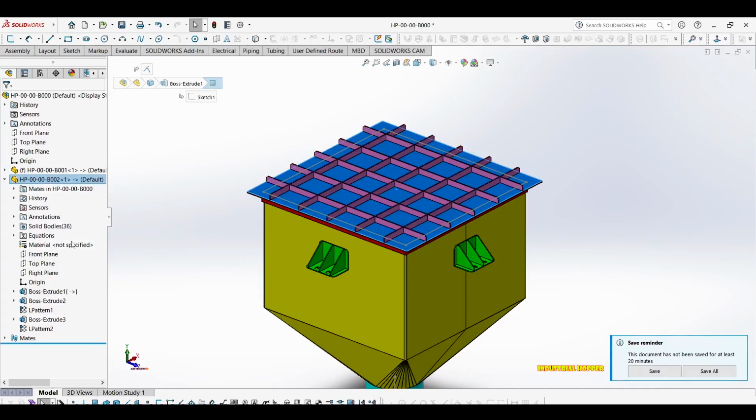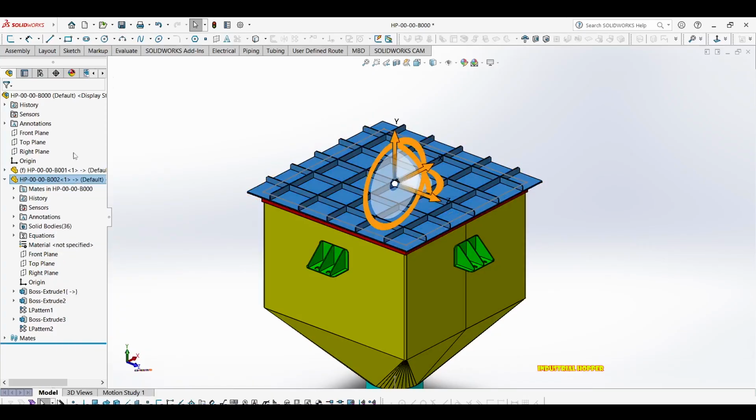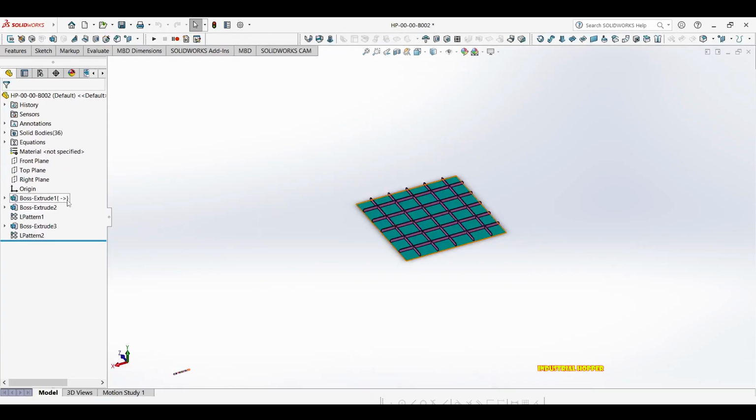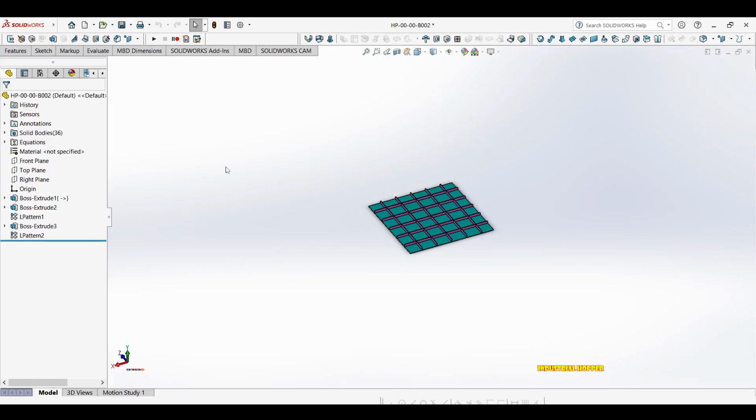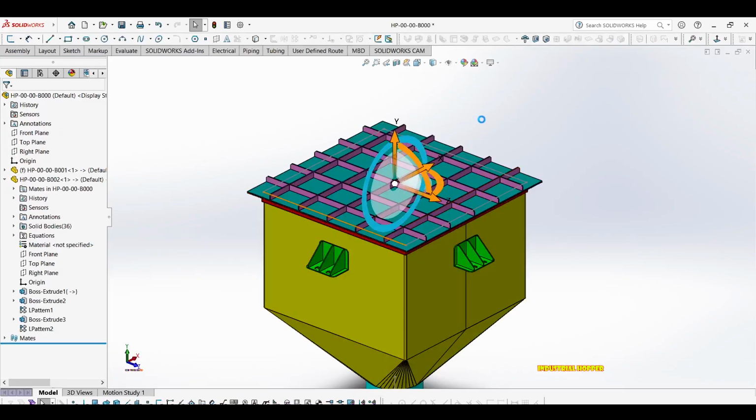And now your references, let's go back and see if it still lost the references. They're back. See, that question mark is no longer there, so they're back. So now you're cool, it's satisfied. Then we save it, we close it, we save the assembly now.